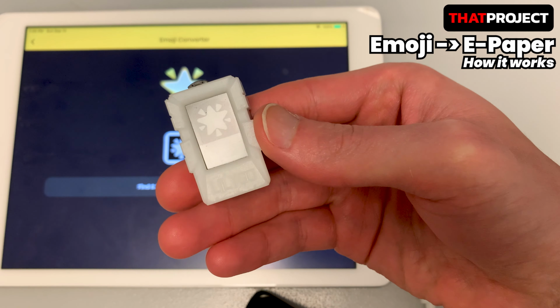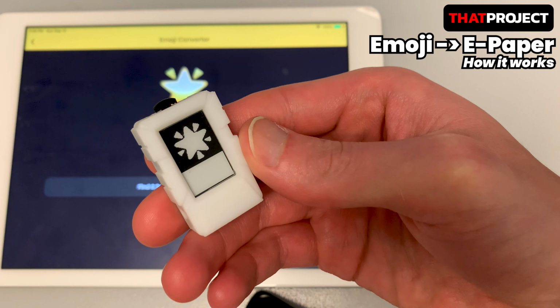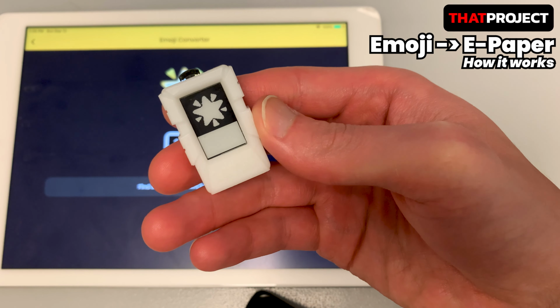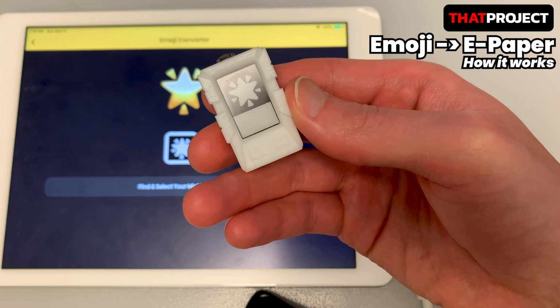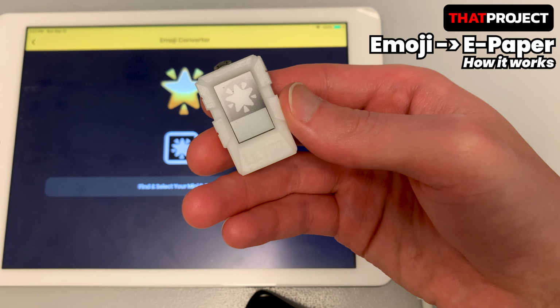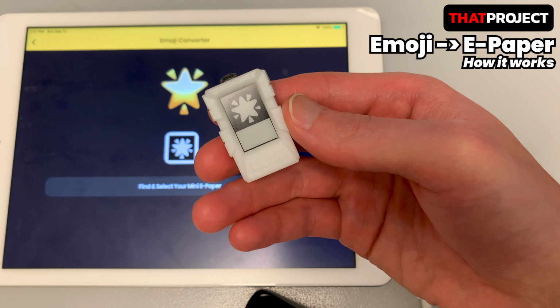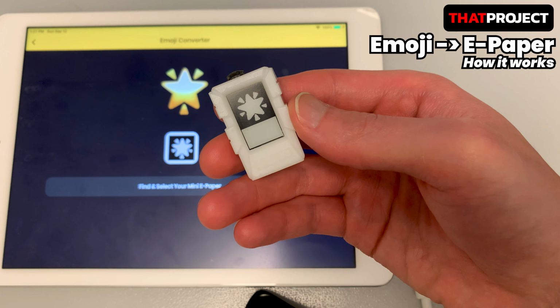In this project, it's able to draw an emoji on the Epaper screen from the mobile application for Android and iPhone through BLE. If we make the bitmap 1-bit instead of 24-bit in the app, the file size will be smaller, so we can update the screen of the ePaper much faster. I will update this part later.